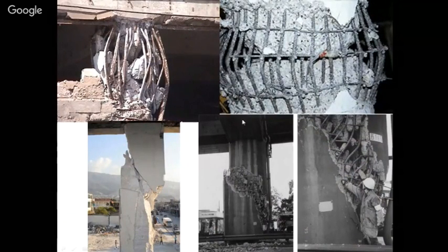The very first image, which you are seeing here, stands for improper construction detailing. Mainly because design is separate and detailing is separate in earthquake resistant design philosophy. Because after proper design, detailing is very, very important in resisting all the forces during earthquake. These images perfectly explain how poor detailing affects the performance of the structure. In all the images, you can see the failures are due to improper ductile detailing in the beam column connection area, and column shear failure in the below images.